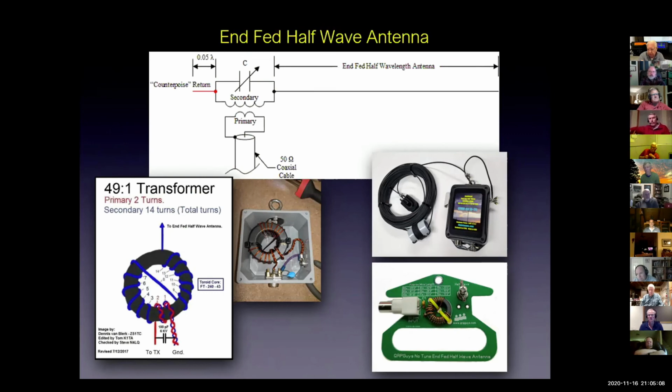Most of these antenna manufacturers with the store-bought end-fed antennas will tell you that if you have less than a certain length of coax, you must use the counterpoise. And over, I think it's 25 feet or whatever it is, then the counterpoise, you forget it. I have one of those end-feds, 130 whatever feet it is, and a resonant 40-meter dipole.